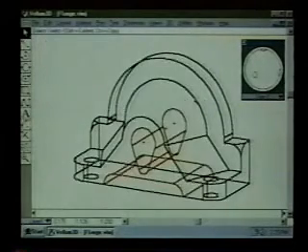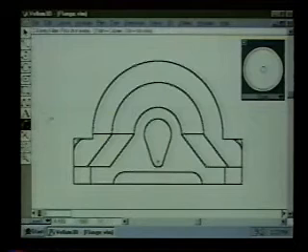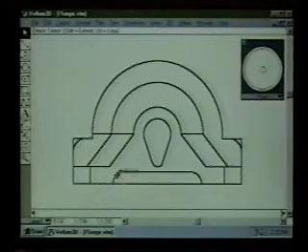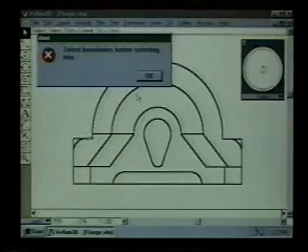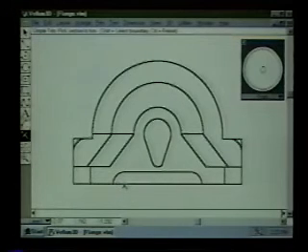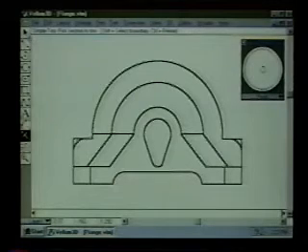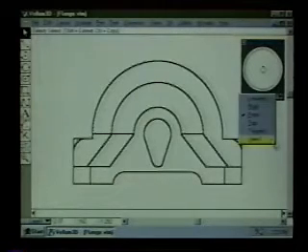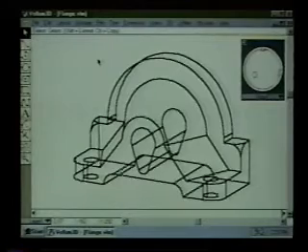I say OK, and then if I change the view to front, I can actually trim out these lines that are down here. Now I can use this as the boundary of a trim. Okay, let me do this again. I need this line and this line to act as boundaries, and then I can get rid of that and that, because there's 2 lines, one in front, one in back, and I can trim out those pieces that are underneath the notch there.